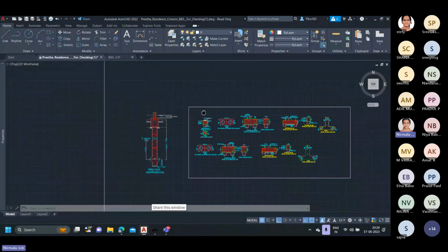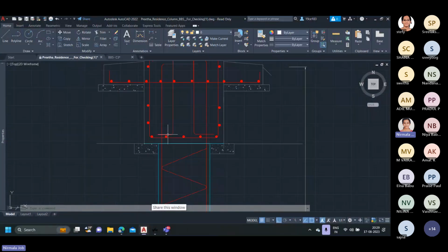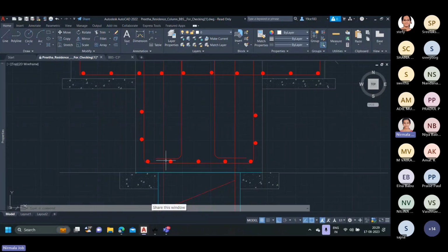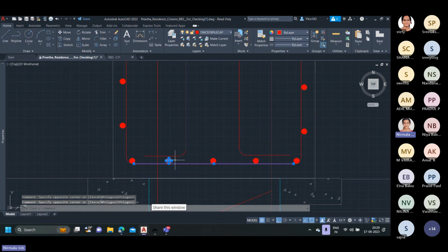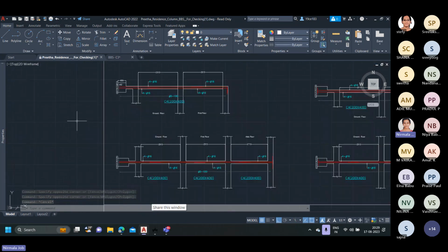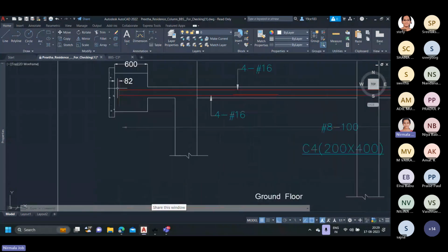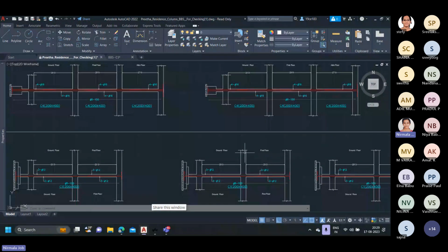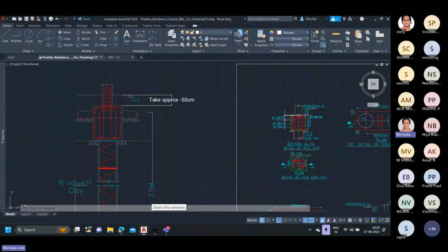So when we look at this figure, we can see that the rebar from the column is placed above the rebars of the pile cap. That is, this particular distance is 50 mm, and these horizontal bars and these circular bars are the rebars from the pile cap. So we need to account for that gap as well. So the total cover will be 50 plus 12 mm from the pile cap rebar plus 12 mm also, that is 2 numbers of bars now.